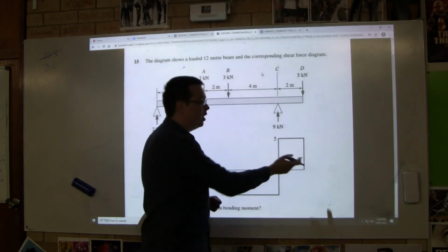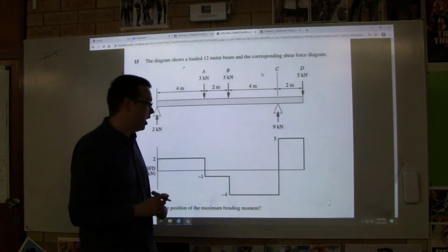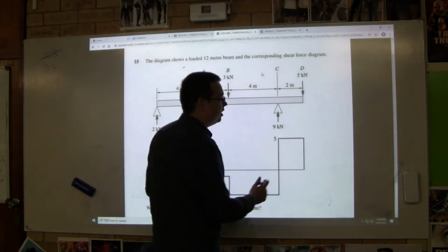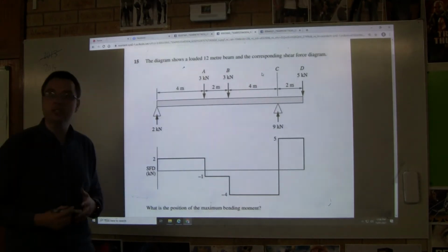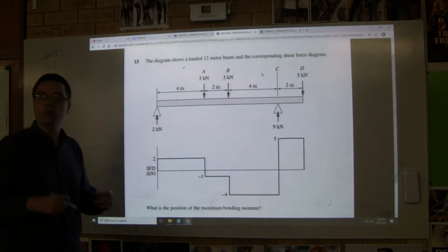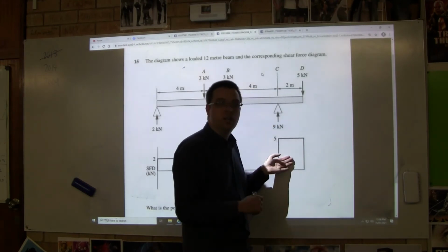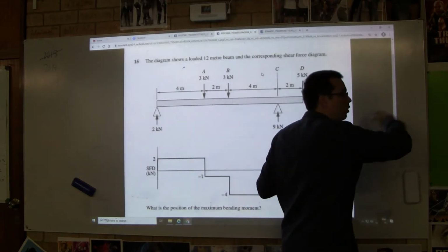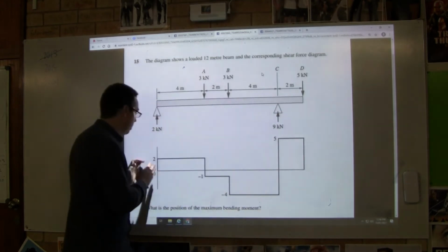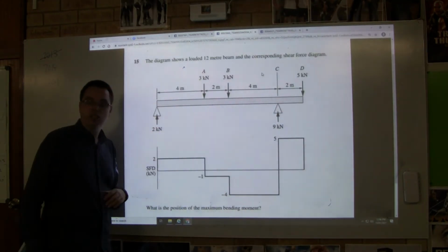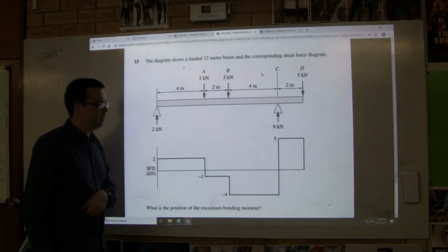One last down, and see how it finished at 0? The end points, the start and finish, have to equal 0. Because if they didn't, the reactions wouldn't work, right? It wouldn't work because, remember, the left-hand side has to equal the right-hand side. And there is no right-hand side over here. There is no left-hand side over here. So those have to be 0 at the ends.